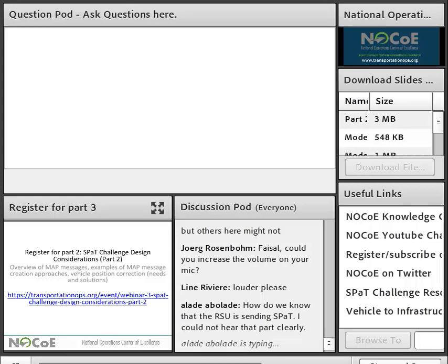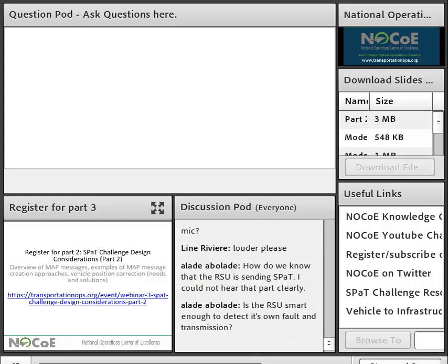The minute, you're correct, it is too crude. So the SPaT message we expect to be broadcasted roughly every tenth of a second. What I believe I said that might have been confusing is in New York City, they don't plan to provide the SPaT data to the RSU unless there's a change. So the RSU is still going to be broadcasting every tenth of a second, but the signal controller in New York City will not provide updated SPaT data unless something changed. So hopefully that answers that question.